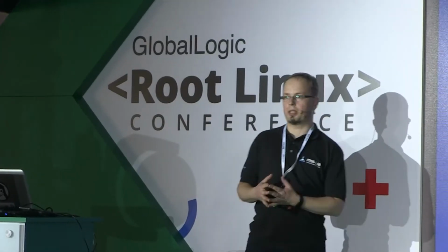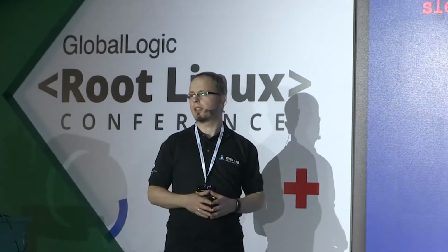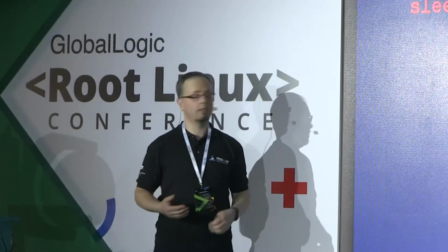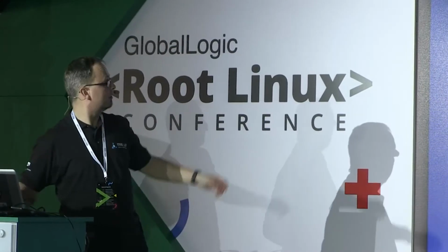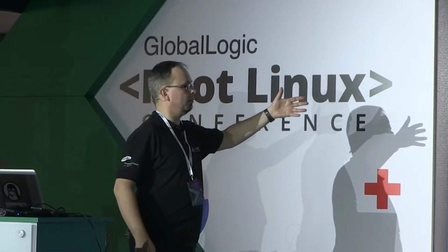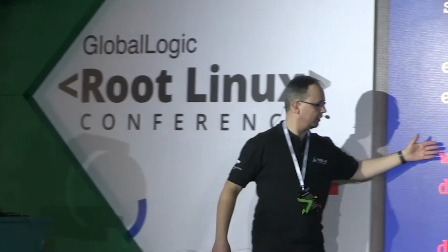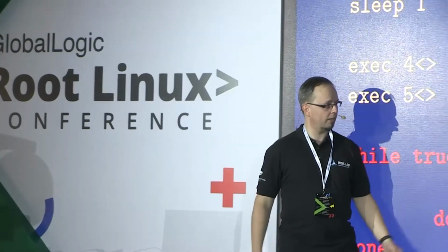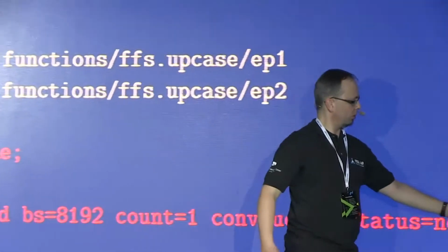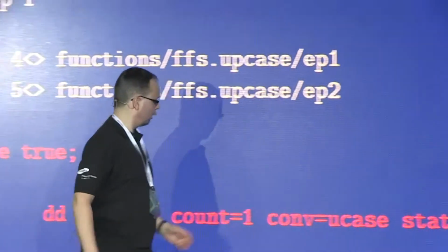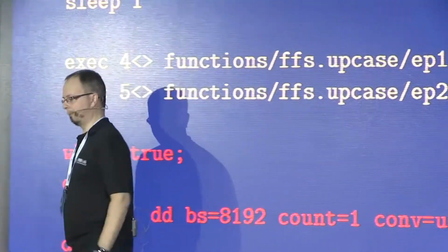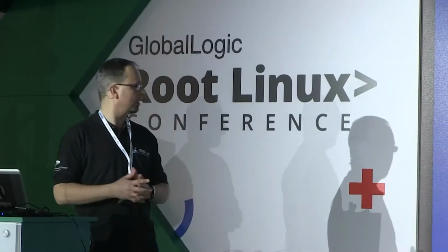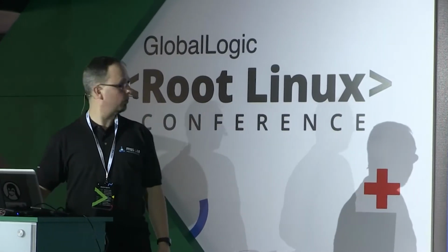So it's a very quick and dirty implementation, so we simply give the kernel some time to create our endpoint files. Now you know this syntax. So we open EP files and keep them open for the lifetime of our gadget. And indefinitely keep copying chunks of up to 8 kilobytes from host output to host input descriptor, converting to uppercase on the go. So that's our shell script implementation of our USB gadget.